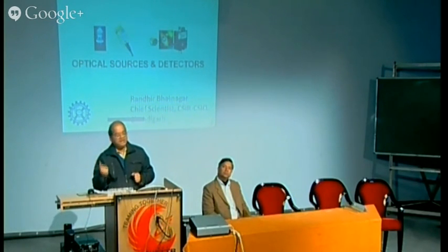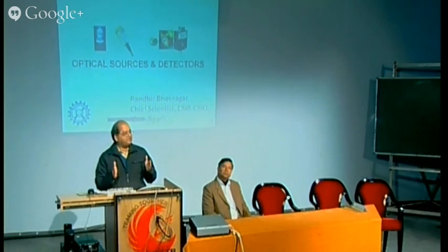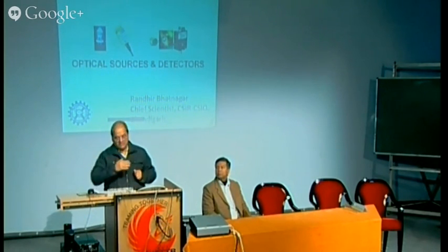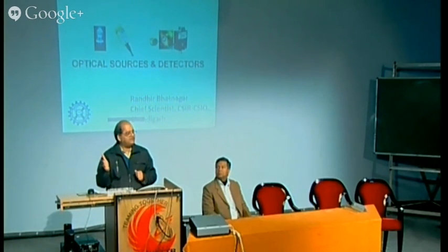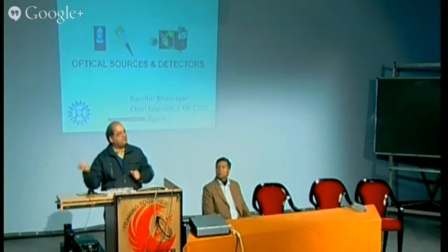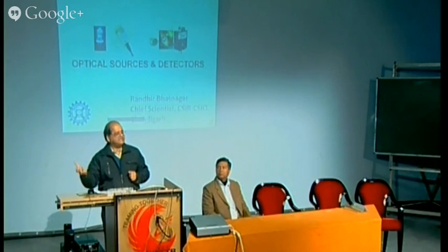A detector with very high sensitivity, because we also discussed that the power levels in the optical fiber are not very high. It is of the order of milliwatt. In order to avoid the non-linear effects, the power levels are kept low. As a result, there is attenuation in the optical fiber, and at the detector, a very small amount of power reaches the destination. Communication is only possible if I am able to detect the signal at the destination. So we need a very sensitive detector.